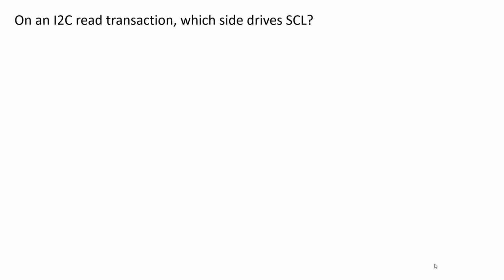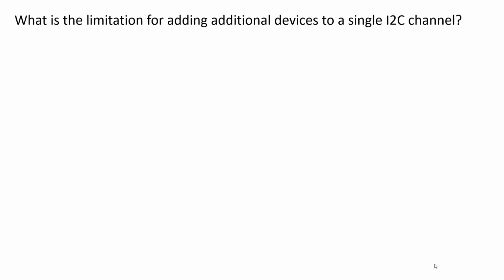On an I2C read, which side drives the clock? It's always the master, right? Yeah. What is the limitation for adding additional devices to a single I2C channel? This one is kind of important. This is an important practical issue. How many devices can I have?